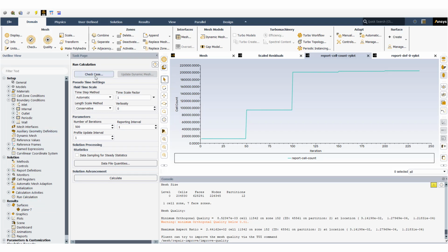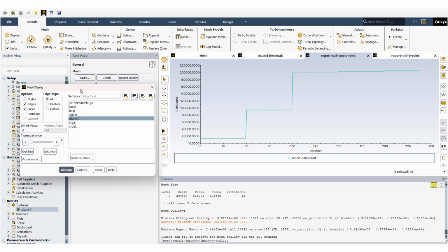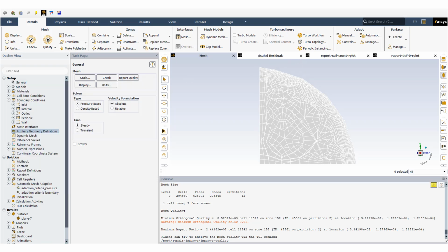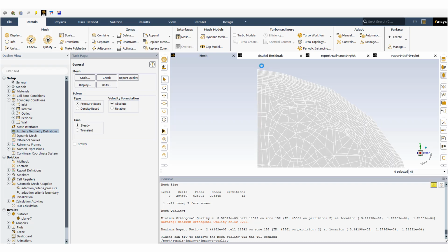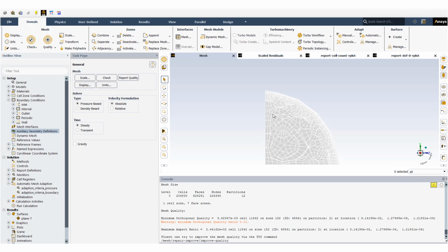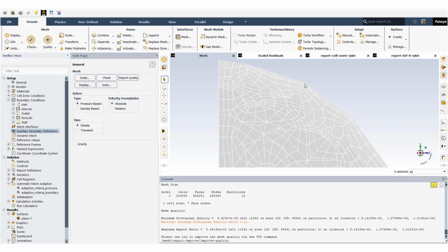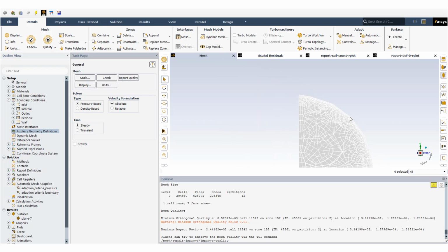And if I also now check the mesh at plane number 7 at the sharp corners, you can see that I have too many cells at this section, which shows that the mesh adaptation did the refinement. For example, see how many more inflation layers I have at the walls, and also how many more cells for the mainstream of the flow. So it is good, but notice these bumps, these sharp corners at this outer boundary that I have.